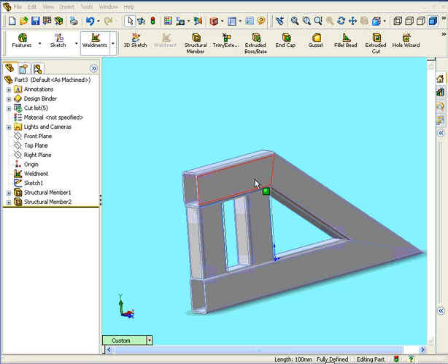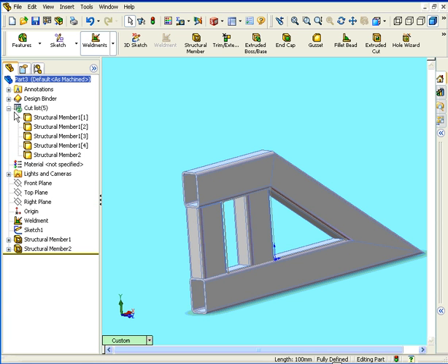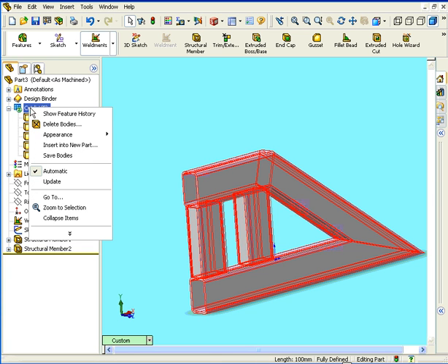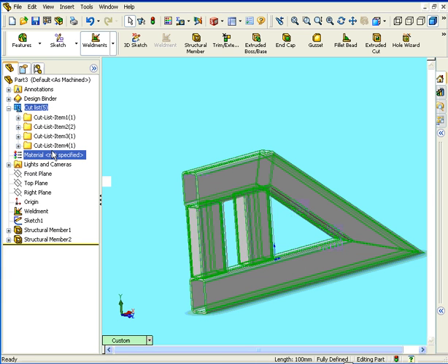One example of this is that in Weldments, our solid bodies don't merge together automatically. With the Weldments tool active, our solid bodies folder now becomes a cut list. A cut list is used in drawing. This green icon indicates that this cut list needs to be updated. Let's right-click on the cut list and select Update.